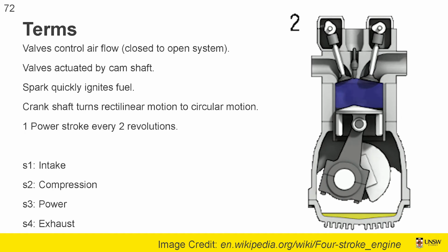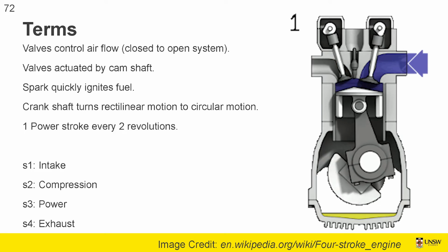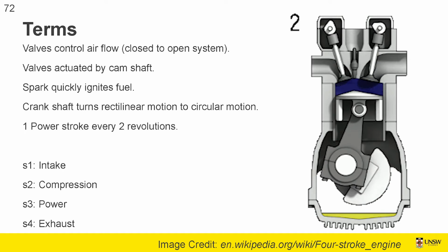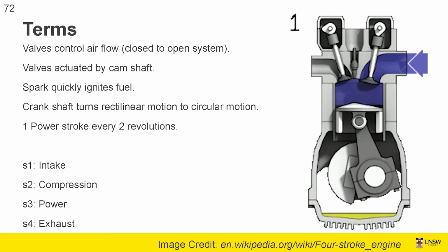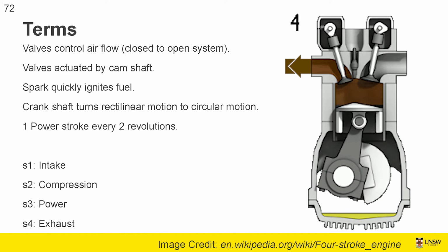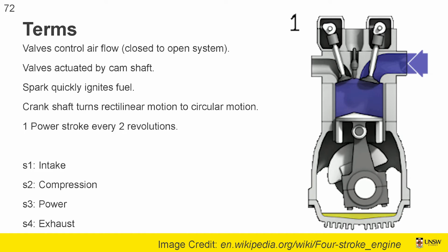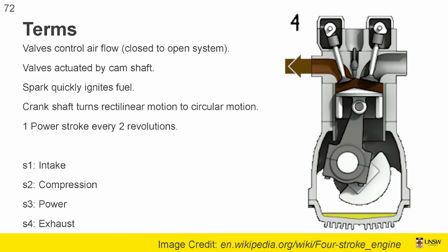Cool, this is an engine. I can look here. These are the 4 strokes. If you're familiar with engines, a potential problem for you is that there's 4 strokes and there's 4 thermodynamic processes, and they don't correlate. So the 4 thermodynamic processes happen only between 2 of the strokes.